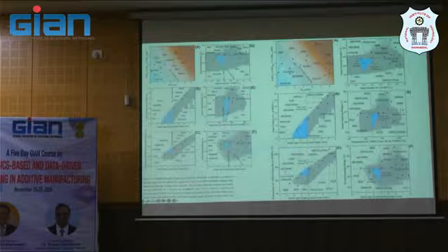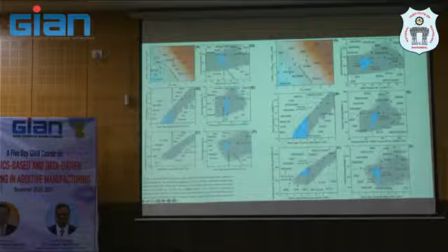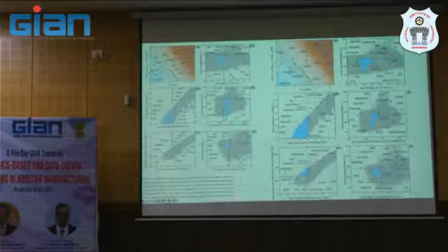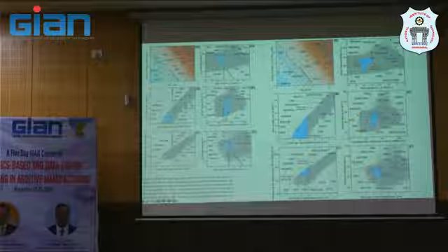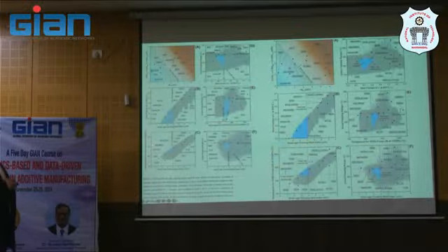And then we can generate the different rankings, because the screening is based on the metallurgy. We identify the window for different criteria, let's say a higher mass fraction of gamma prime at 900, strain age cracking (because we're talking about cracking at that time), and creep life at 1000 degrees centigrade at 137 megapascal.